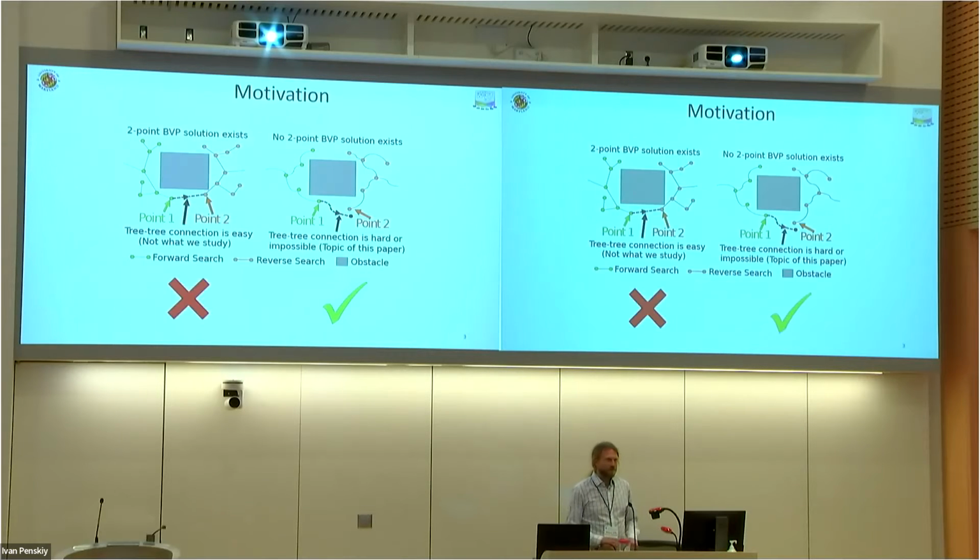So a little bit of motivation for this. In search problems, it's well known that if you have the ability to do bidirectional search, then you can get significant speed improvements, even though the big O runtime is essentially the same. It's a volumetric expansion, one way to think of that in a high dimensional configuration space. And once these two expanding balls touch, then you're essentially done. The amount of volume contained in two balls of half a radius is much less than a single ball of a full radius. That's a very high level, sweeping tons of details under the rug, of why this is important.